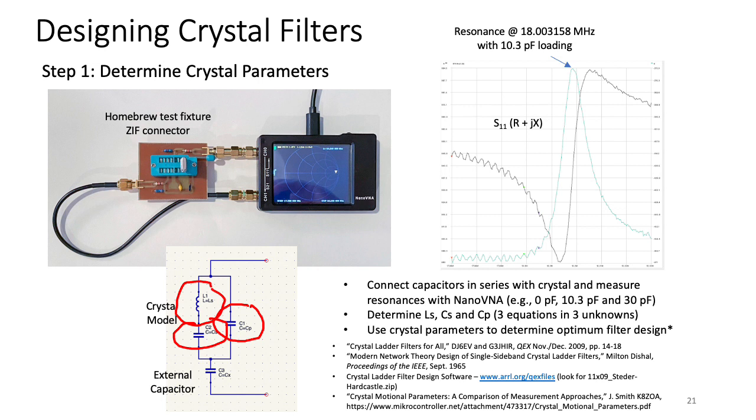To measure these 3 parameters, we're going to use the Nano in kind of a unique way. We're going to look at the impedance that is seen by the Nano and look at the points in the impedance where we get an abrupt change due to the resonance effect of the crystal. In order to measure these 3 parameters, we'll need 3 equations, basically. And we have 3 unknowns, 3 equations will do it.